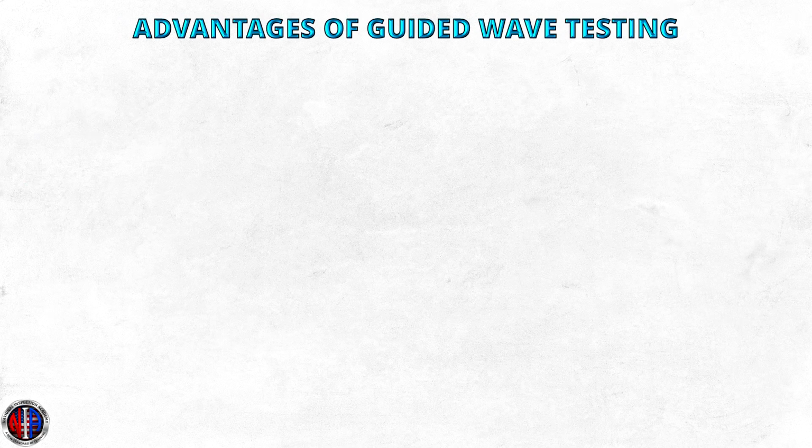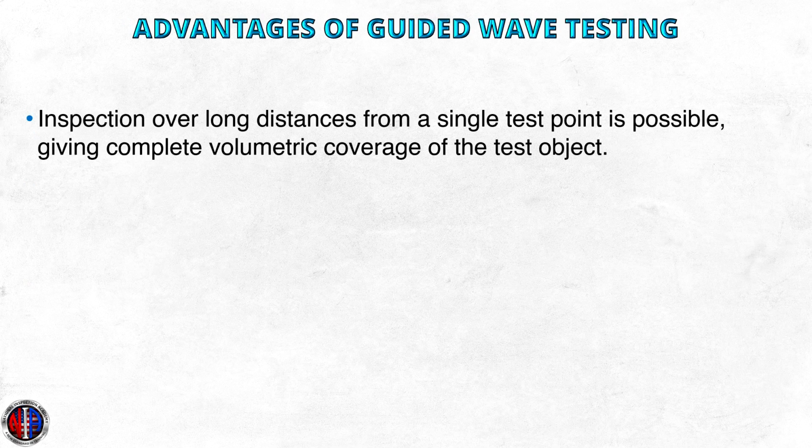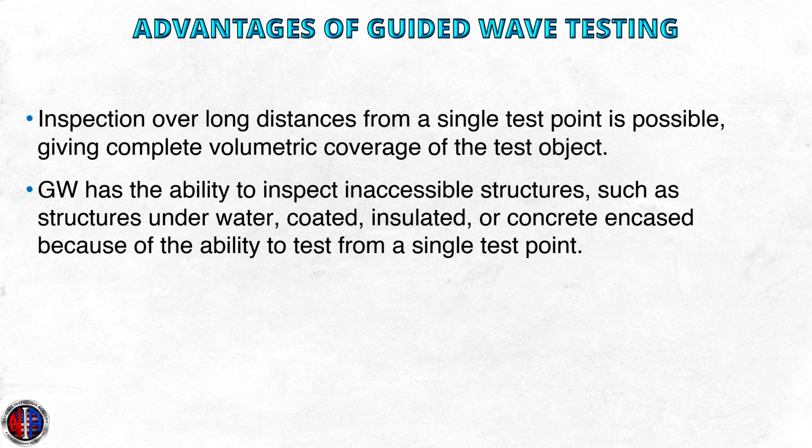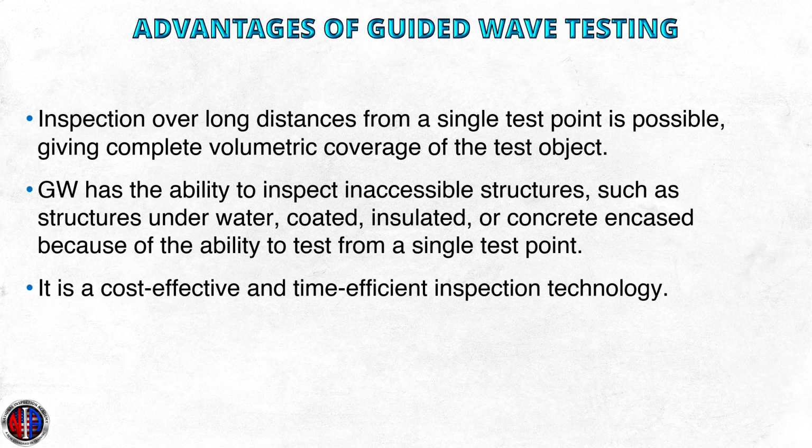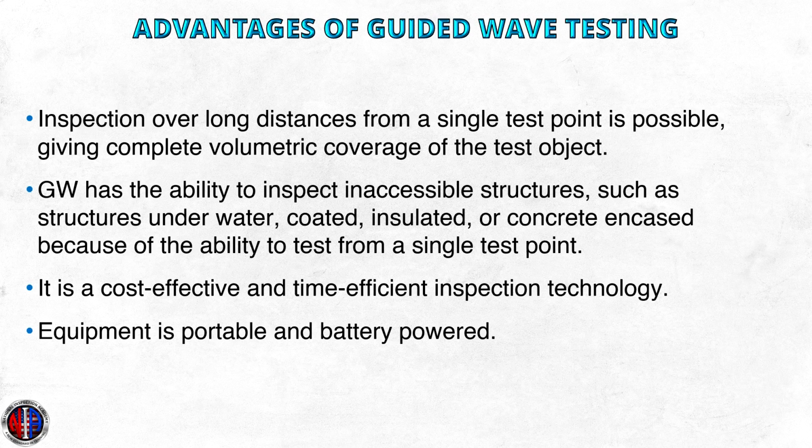Advantages of guided wave testing. Inspection over long distances from a single test point is possible, giving complete volumetric coverage of the test object. Guided wave has the ability to inspect inaccessible structures, such as structures underwater, coated, insulated, or concrete encased, because of the ability to test from a single test point. It is cost-effective and time-efficient inspection technology. Equipment is portable and battery-powered.